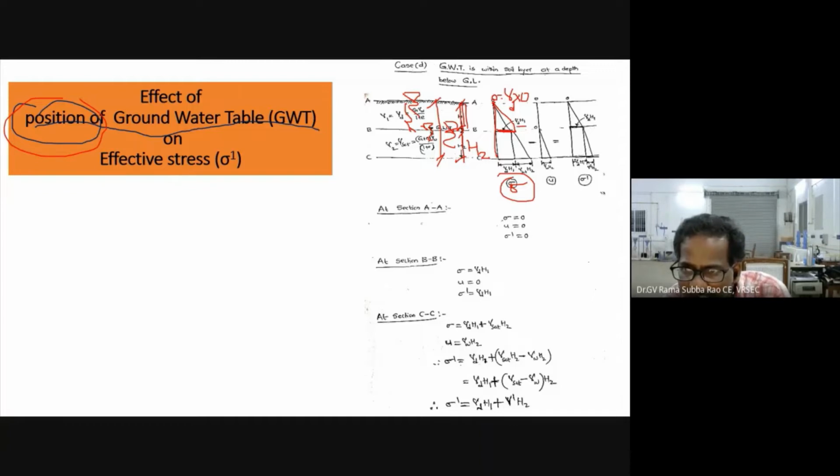Once we enter the second zone, the saturated zone, in fact the submerged zone, the dry contribution is going to be constant, because gamma D into H1 is already acting. So it will be continued, and now we are going to a rectangle. The reason I am drawing a rectangle is that gamma D into H1 is constant. Now we are seeing a rectangle here.